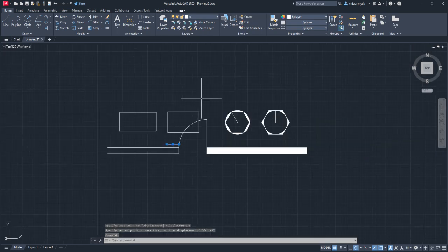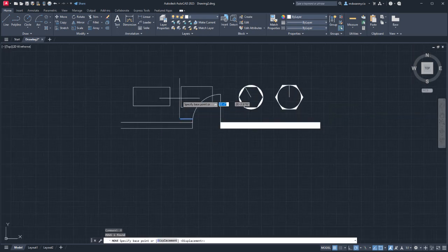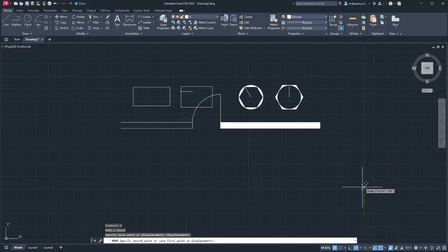So what I want you guys to know when you use the move tool is find a clear space to reference. When you have the thing selected, you don't have to click on it to move it. So I'll find a clear space outside of the rest of my model, and I'll use this as a reference for how far and which direction it needs to go so that I don't end up snapping to other stuff in my model. So I can move this and there's no issue because it's not mixed up in all the other stuff.